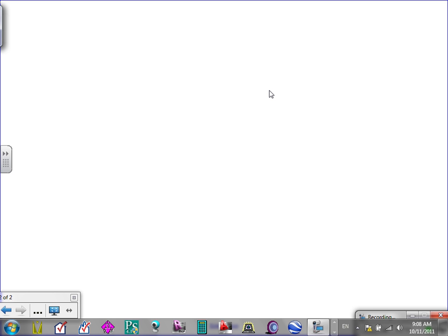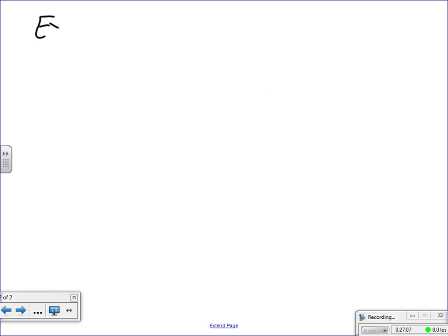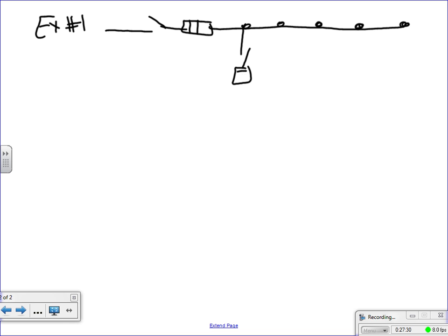Okay, I'm going to use a single phase system. Here's the example. Example number one. What I'm going to use, guys, is the following. I have a disconnect with a fuse, and I brought it right here into a gutter. Inside my gutter, I went with my fuse, overcurrent protection device, conductor, controller, overload, and a motor.